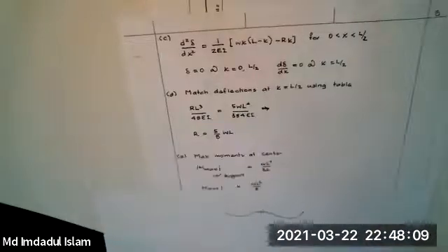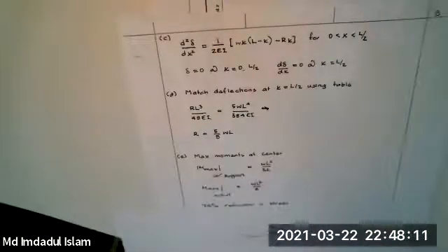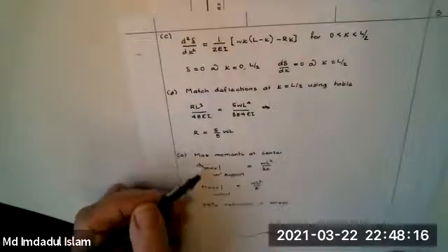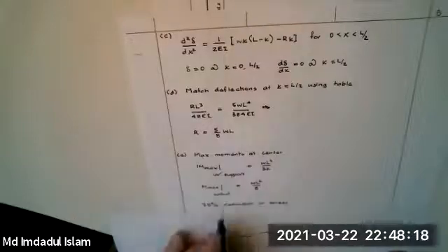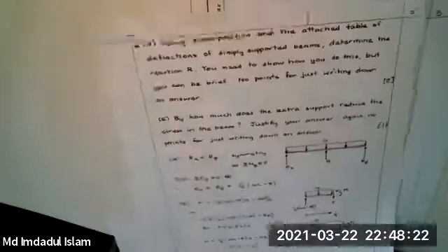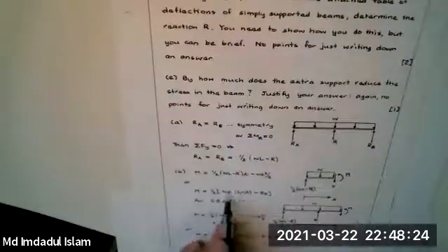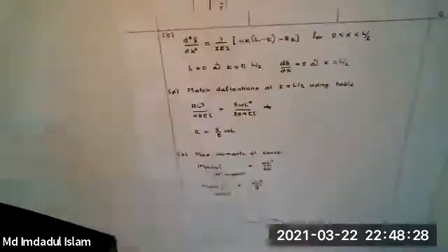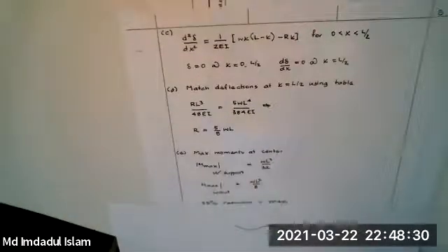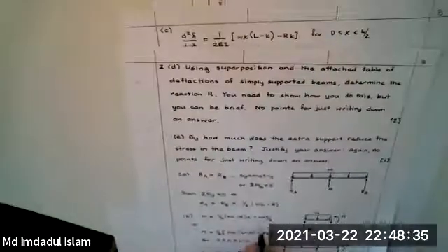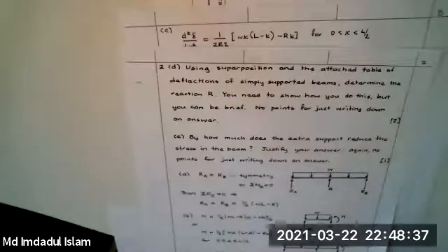The last problem here was the occasional tough 1-point question on these exams. This is a little more difficult to do. The maximum moment's at the center. Without the support, you could actually get it. You wrote, without the support, it's just this and this. This is a parabola, it has a maximum at the center. You substitute, you're going to get WL squared upon 8. When you get the maximum moment from something like this, for that matter, you get the same thing here.